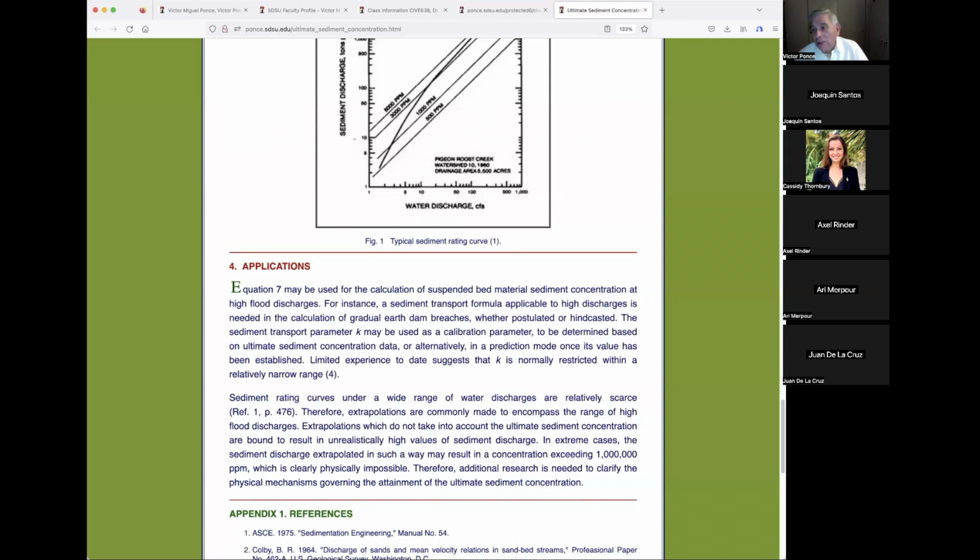There's an actual book that I put together with one of our students several years ago, a collection of about 30 dam failures starting around 1900, so 120 years ago. How is it that they failed and why they failed? The common denominator of all these failures is that it rains a whole lot, it overwhelmed the spillway, it broke through the breach, and it caused the breach. So then the question at that point, and this is where we're headed, is how long is it going to take for the dam to fail through the breach? And that's interesting because the shorter the time it takes, the worse is the flood.